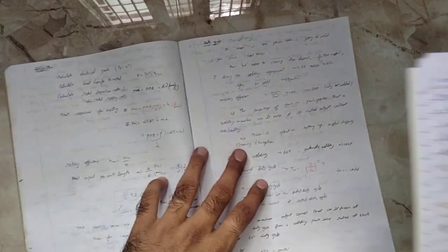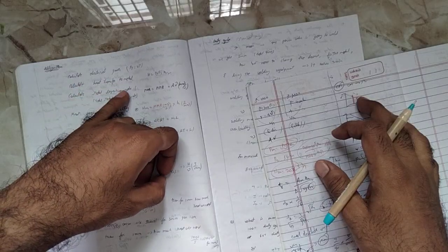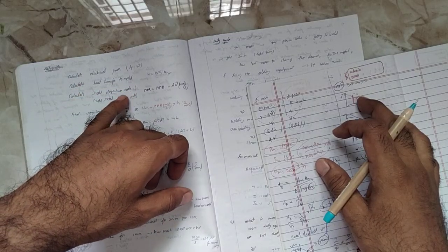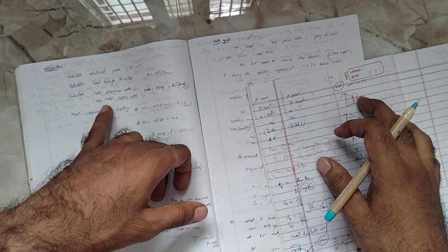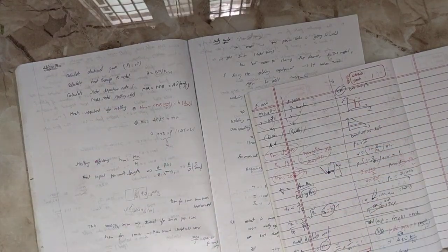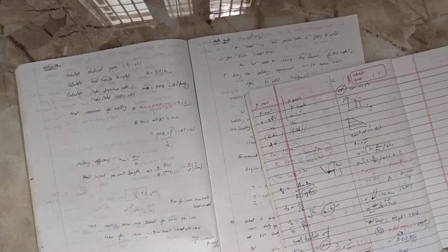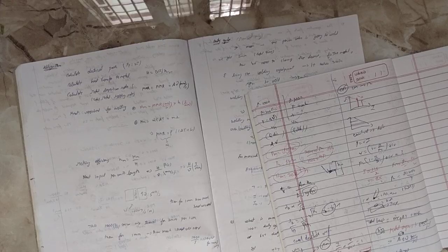You can see about this. Calculate electrical power P equal to VA, and calculate heat transfer equal to VA divided by heat efficiency. Then we can calculate the metal deposit, and the heat required to fill the molding. So Hm equal to m Cp delta T plus m L.